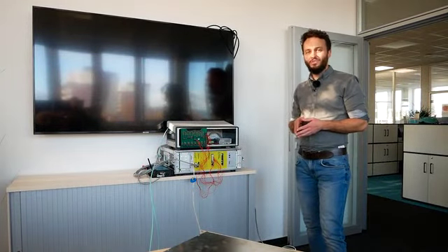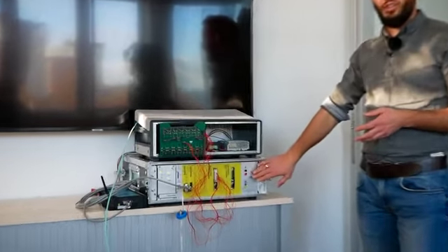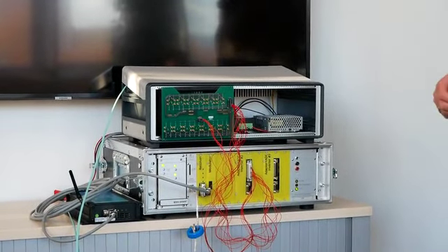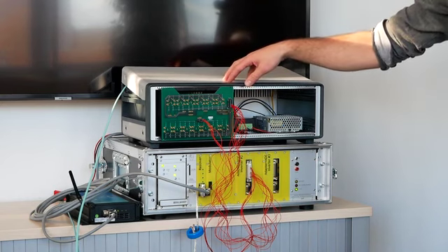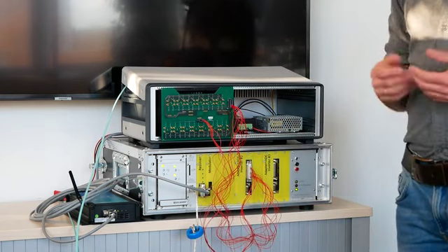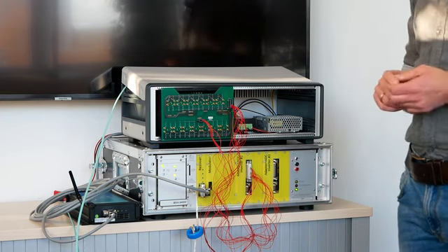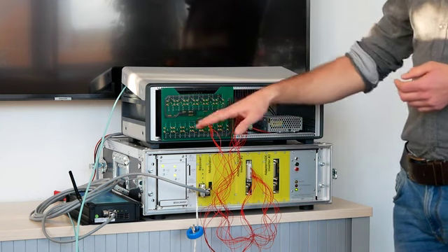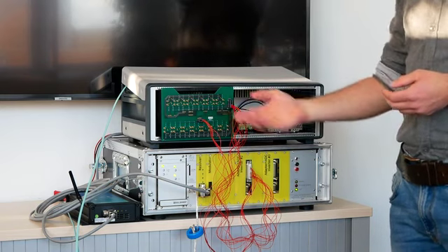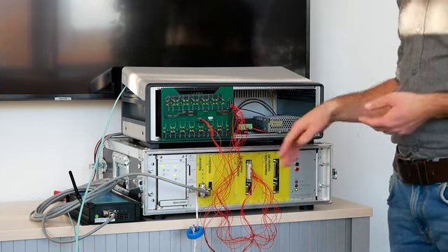So, let me quickly introduce to you the hardware setup that we used for our proof of concept. The central part here is the unit under test, which is a control unit for a state-of-the-art inverter. And we have here what we call our fast signal interface. Through this interface, we read in the PWM signals, which we can do up to 1 megahertz switching frequency. And we have also at the same time the interface for the current sensor emulation, where we feed the emulated signals from the current sensor back to the unit under test.